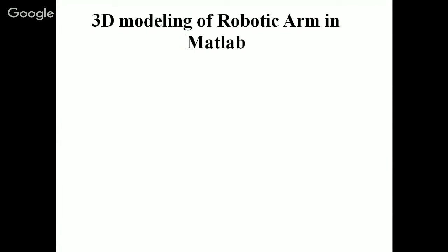At first, we can design and simulate the robotic arm in MATLAB and Robo Analyzer software also. Simulation is necessary because we have to simulate before making the hardware project. If we make the hardware project and it does not work properly, then there is a loss of money and time. So we have to simulate the robotic arm in simulation software. It is also possible in MATLAB. We have to add the robotics toolbox in MATLAB, and this is the simulation procedure.